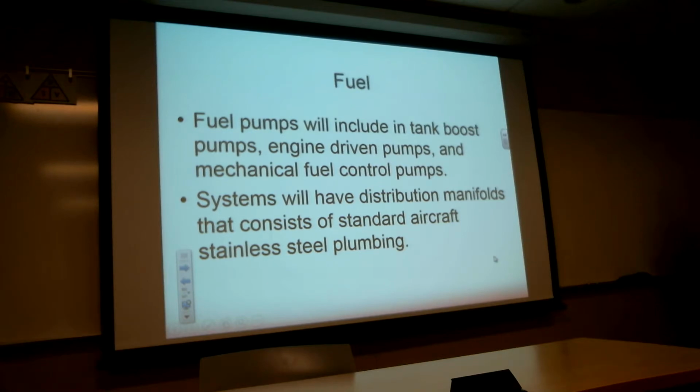So how much fuel does a big turbine engine pump? Well, I can tell you this. I disconnected a fuel control on a 787, and I had a bucket. Actually, I had two buckets, two Homer buckets. It filled from the wing to where the engine hangs. It filled 1.5 buckets of fuel just in that line that comes off the wing. That line is about 3.5 inches in diameter. So you know you're flowing some fuel.